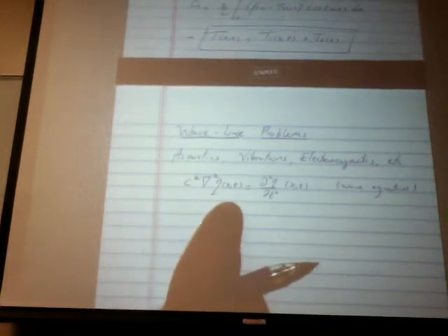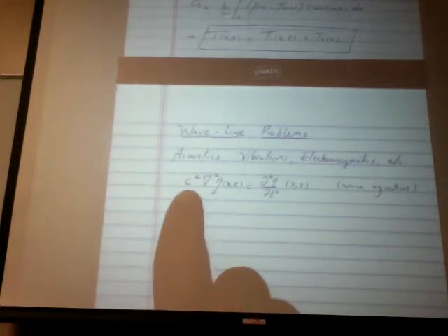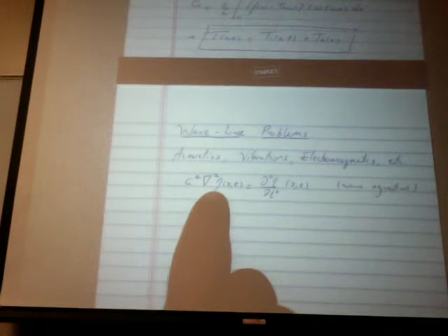For example, if this is the vibration of a membrane, let's say a membrane that is constrained all the way around, then c will be related to the modulus of elasticity of that membrane. So the stiffer the membrane, the faster the wave will propagate, right? And eta would be just the amplitude of the wave, okay? The position of the membrane with respect to a datum at any time, or z, okay?